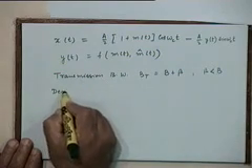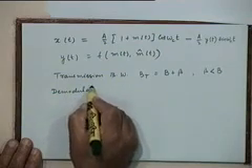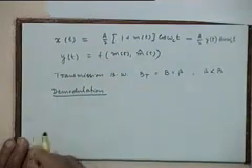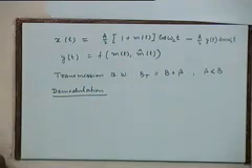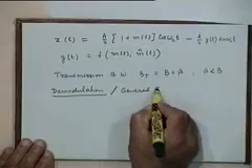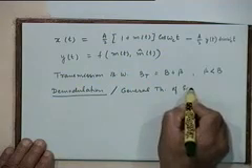Now demodulation is what we would like to spend some time on, because that leads to some crucial questions and answers. In the process we will also look at a general theory of sideband filtering, which will include SSB as a special case, right. So VSB is a general case and SSB becomes a special case in which beta is equal to 0, right. So we will in the process also discuss a general theory of sideband filtering.